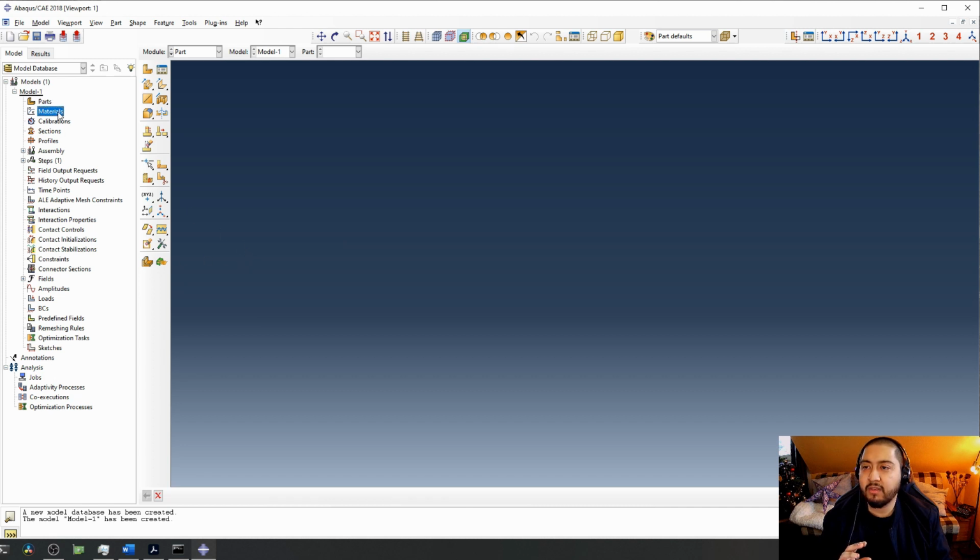As you probably know already, in Abaqus you have different properties for the setup that you need to define. Usually we do it step by step in order not to get lost during the process. We are going to start with the importing or creation of your 3D part, and then go to the material section, in which we define material properties. Then we are going to create and define sections, assigning them to the materials that we created.